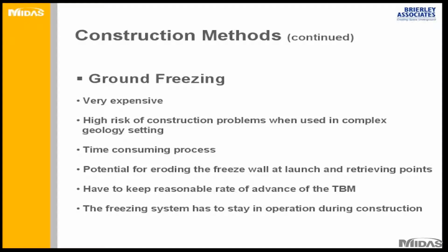The last alternative is ground freezing. If you start using ground freezing, it's a very expensive and time-consuming process. One serious concern is the potential for eroding the freeze wall. I will describe one case history where you can end up collapsing or failing the whole shaft because you start eroding the freeze wall.